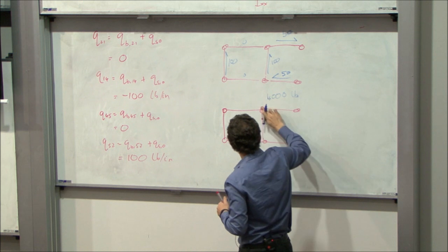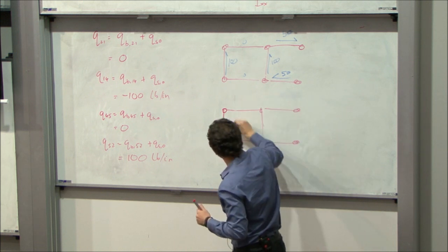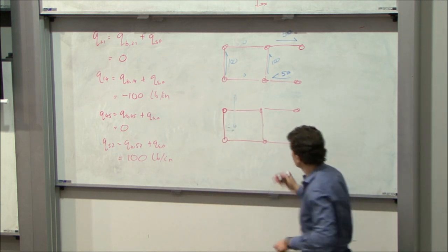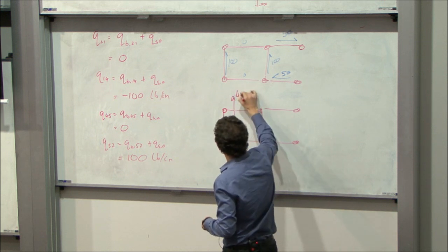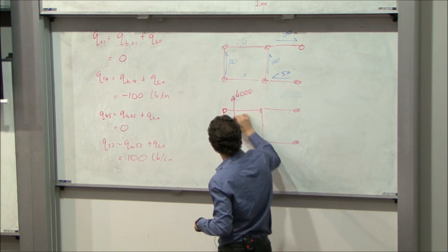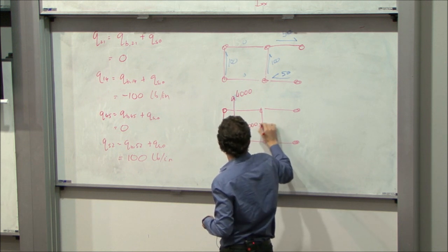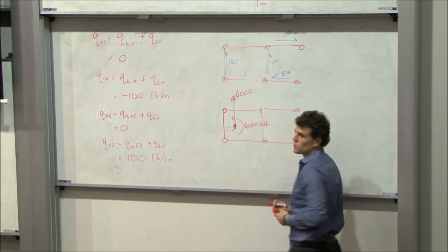Move your shear force to the shear centre, and apply a moment of 4,000 times 14 to get to the same force system as we had before.